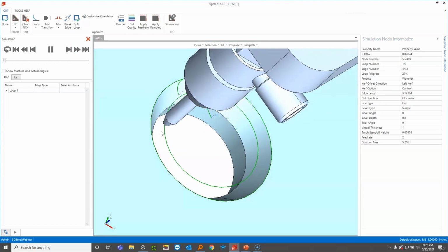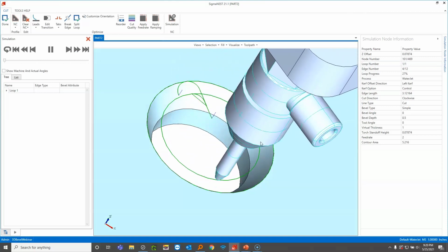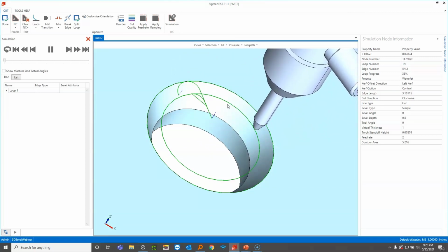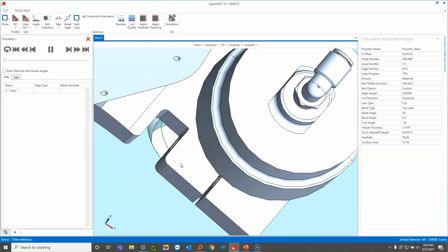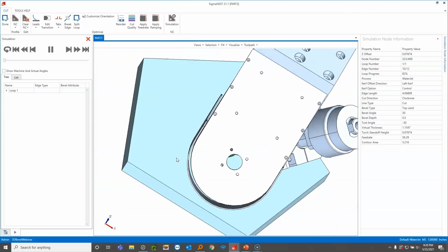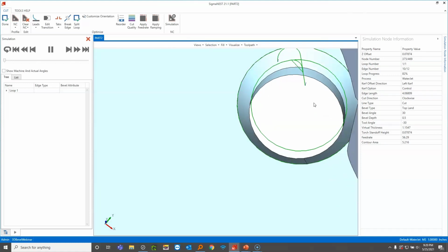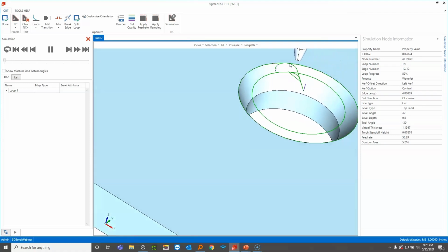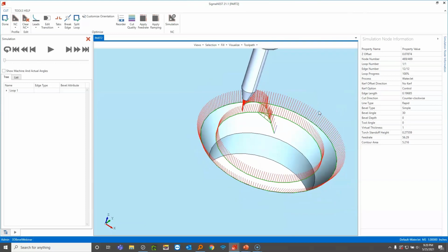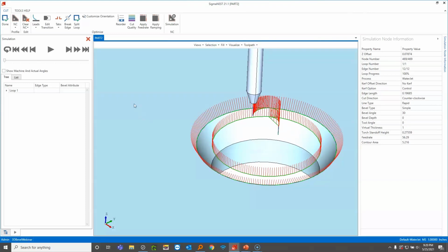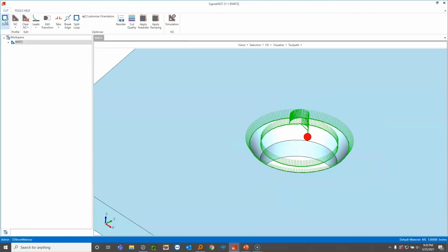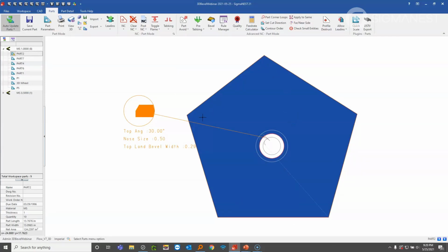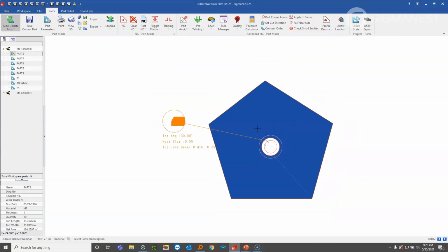All right, so it cuts this straight cut portion. And it's going to come straight out like that, and you see it goes right into the next one. It's going to come all the way around and finish it off right over there. Yep, and it comes right out. Cool. So I'm going to go ahead and close this. And now that I like what it's doing there, I'm just going to hit done again. And SigmaNEST 2D takes care of the outside portion. In the middle is 3D.